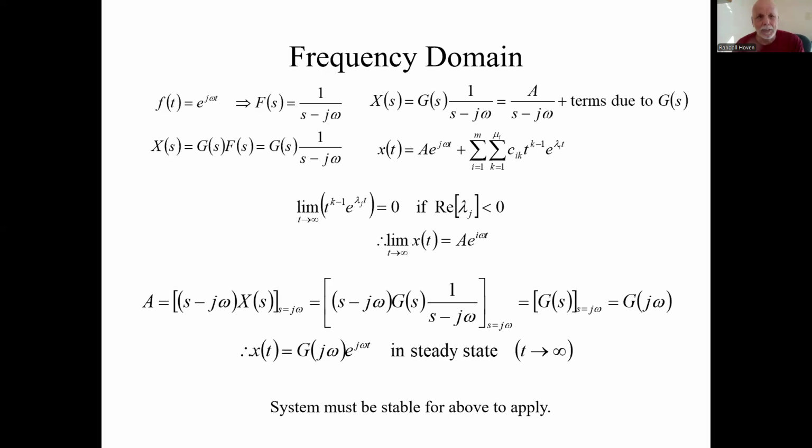This module of my videos deals with a very quick review of linear systems. And in the previous videos on that, I talked about the time domain analysis. And the Laplace transform was a significant tool used there. And this little relationship here was a significant result of that, which says the output of a system in the Laplace domain is this product of the transfer function of the system and the Laplace transform of the input.